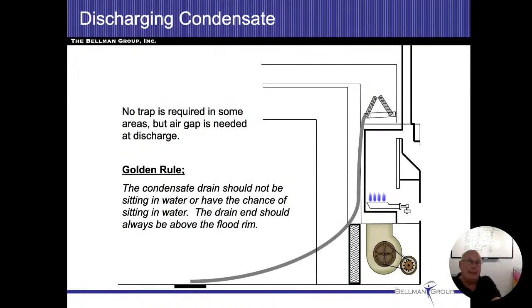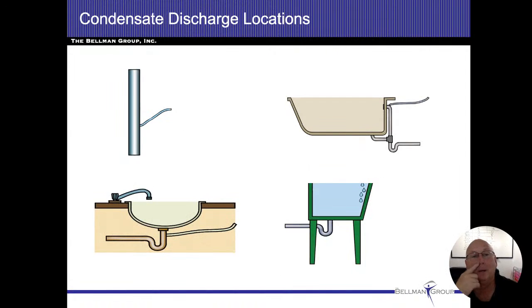So we know we're going to be getting condensation coming from this coil. We have to collect that condensation, and we have to drain it to a floor drain or put in a pump, someplace where it's going to go to a safe location. All right. I don't really get too much into these things. If they're going to put it into the soil stack, as it shows in the upper left, you need a trap of some sort there. We don't want to take a chance of letting that sewer gas come back into the house, and then we're circulating it through our fans. It's just not a good idea.